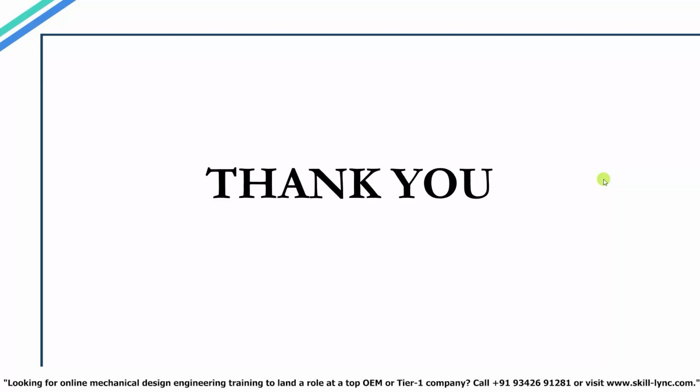In this video, we are going to get started with piston design. So let's first create a new sketch. Let's click on new and then new part, click OK. Then we are going to make sure our unit system is set to millimeters. Now we are going to select the front plane, click on sketch.